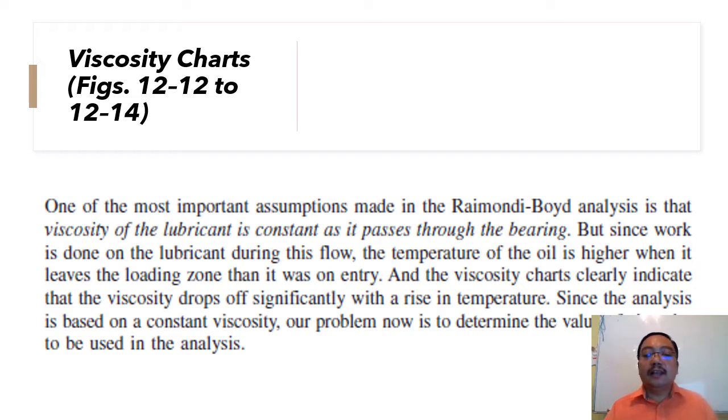Everyone does that. But in actual practice, when the lubricant enters here and goes out, along the way processes happen, the loading, the temperature rise and everything. So number one, temperature going in and temperature going out is different.